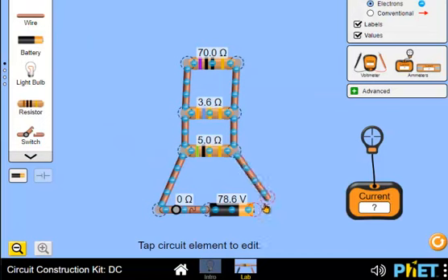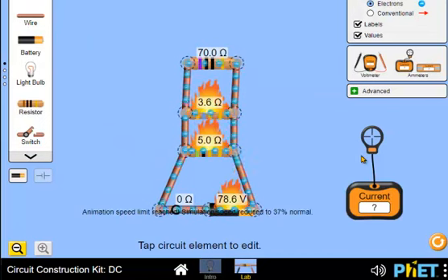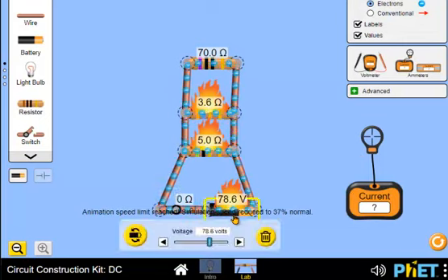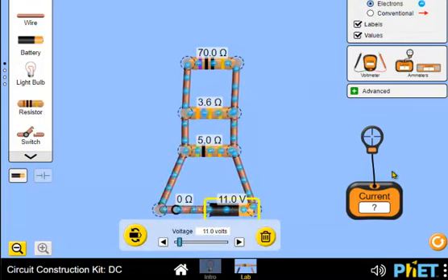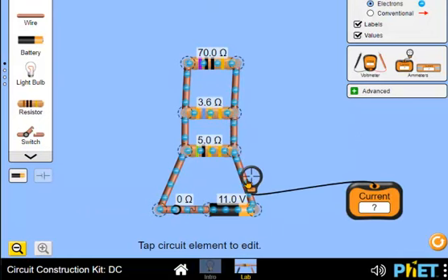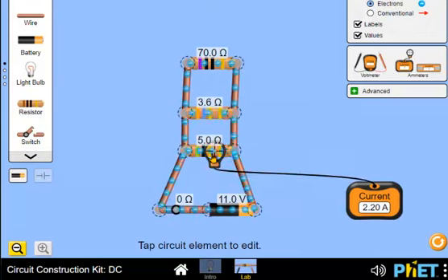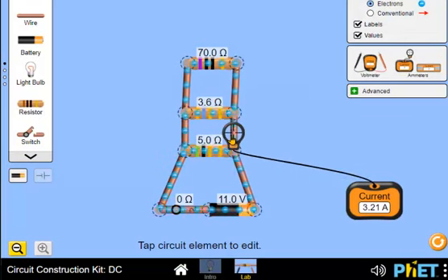And now I'm going to try the same thing when I put... Whoa! Okay. So get the voltage down, and I put the fire out. Oh, okay, that's a little better. Here I'm going to measure the total current. By the way, you see right now here, for example, 5.41 amps. Notice when I measure here, 2.20 and 3.21. They add up to the total current, right? That is, of course, the junction rule, Kirchhoff's junction rule.